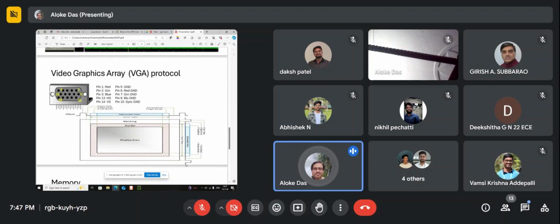So essentially, what is happening when you are trying to create a new frame, you have to do this vertical thing. Then during the horizontal sync, when it is low, you draw each pixel, then you scan like this, one by one, each row.